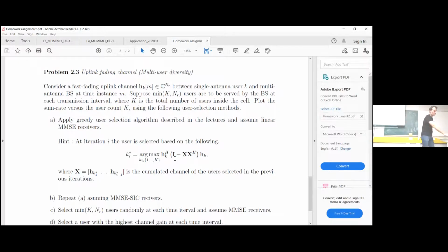All right, so we covered the dual uplink SINR expression. Now, let's switch back to the original downlink, okay? And rewrite the received signal from a user K perspective. If you think about user 2, which is in the middle, here we assume that the encoding order is reversed with respect to the uplink.